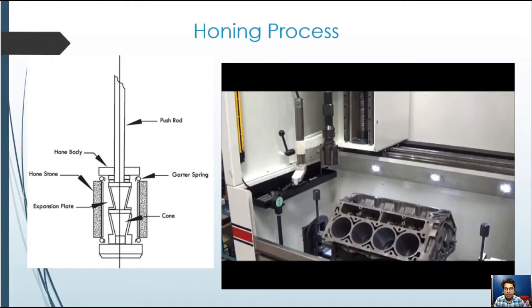Honing is an abrading process for removing stock from metallic and non-metallic surfaces. It is used to correct local irregularities such as ovality, waviness of the axis, or non-parallelism of cylindrical features, and to develop a particular texture. Honing is the application of bonded abrasive stones to a surface.